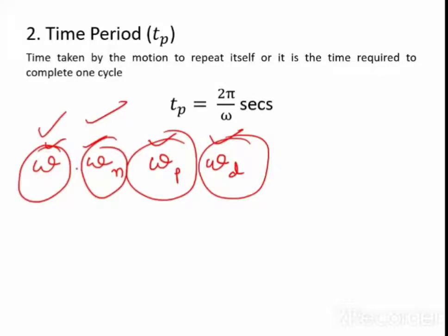Omega is the frequency of excitation. When omega is equal to omega n, you will get resonance. What is resonance? Excessive amplitude, meaning excessive maximum displacement. The system will fail. As an engineer, you have to avoid resonance. Your first aim is to avoid resonance in any system, and that is why omega is, most of the time, not in your hand. So you have to design omega n accordingly.